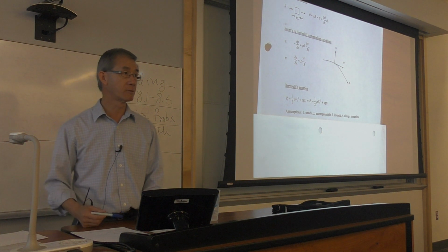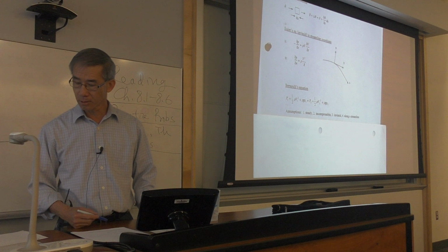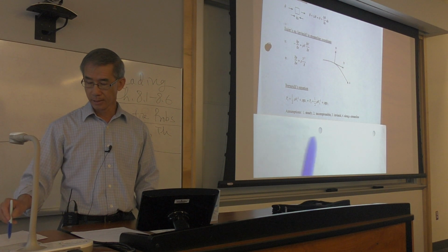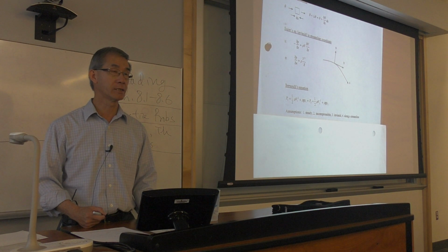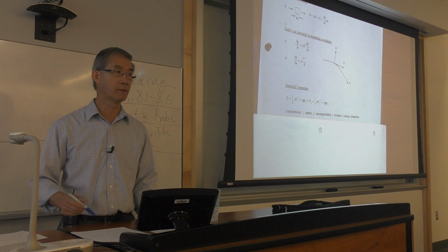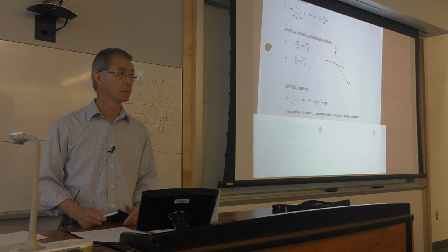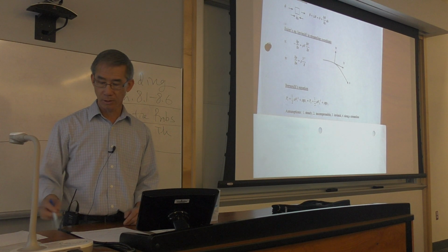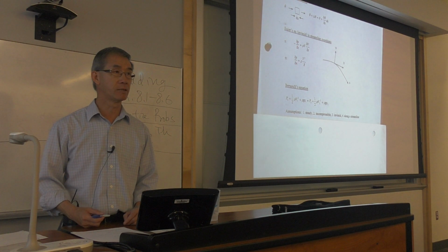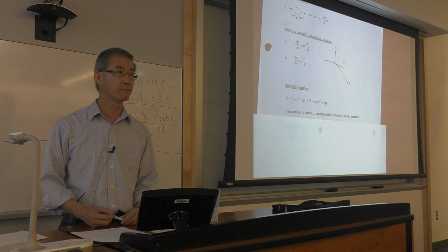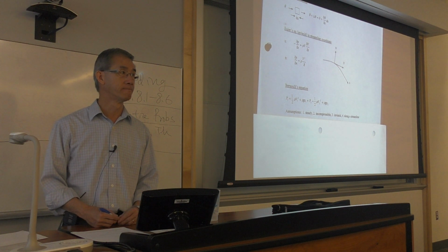Inviscid, because we are dealing with the Euler's equation assuming no friction. The incompressible assumption, constant density, is only needed when you integrate the Euler's equation. It's very detailed, but I hope you should be able to comprehend that. It wasn't an original assumption from the get-go. It's only when we integrate that we have to assume the density to be constant in order to have a closed form, very nice, simple Bernoulli equation that we love to use.